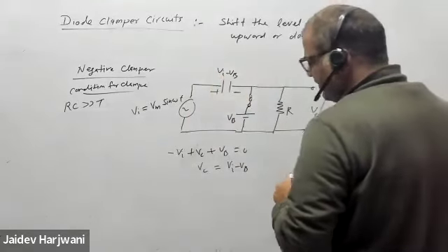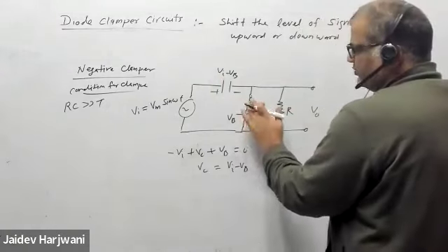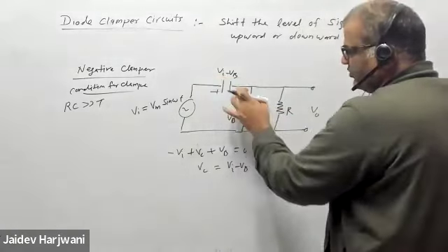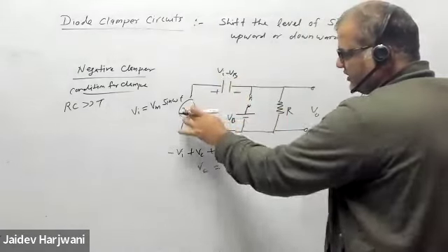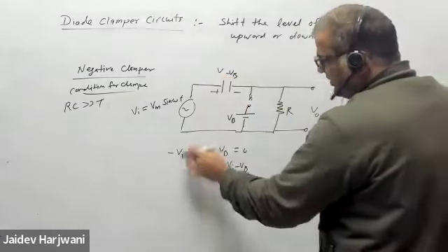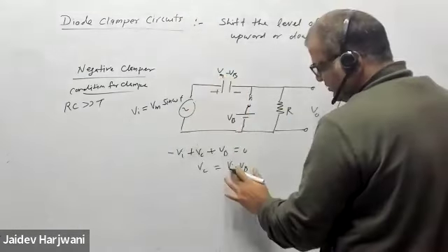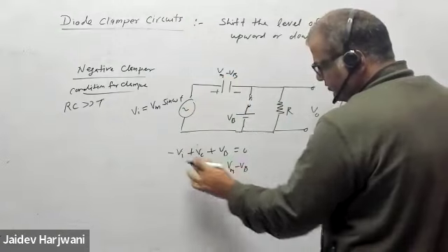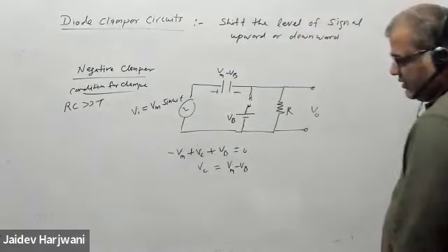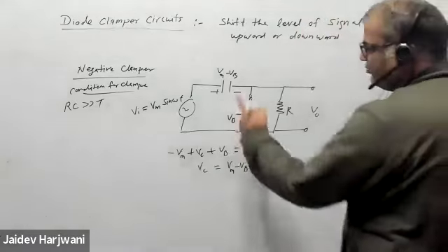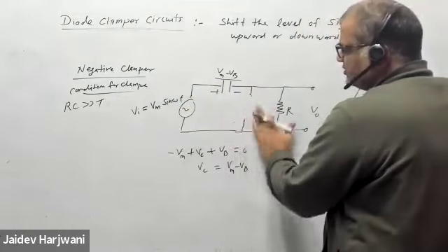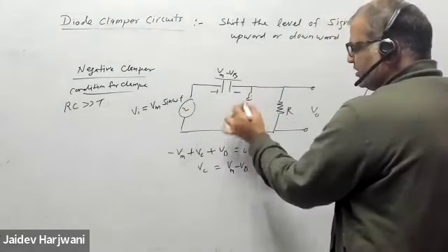And once it is completely charged, this circuit will get open, because this voltage is always greater than these two voltages. I'm taking the maximum value of this one, so the capacitor will charge up to Vm minus VB. Now this voltage always balances this one, and this will go open, so you can remove it because it's open, nothing is there.